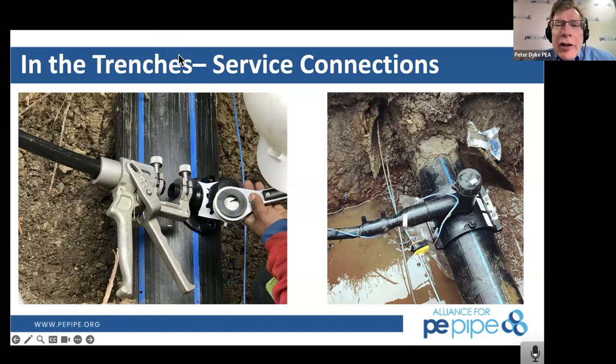Yes, Pete. I tend to look at it as a transition. Castleberry now uses electrofusion connections. And a lot of utilities, before they get fully comfortable with electrofusion, solve the big question by using polyethylene mains, but then they still use mechanical. That image on the right is an interesting one too. It's a self-tapping electrofusion saddle, and you just unscrew that top and cut into the wall as Alan described.